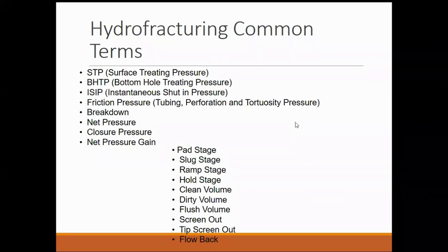Net pressure, I'll cover in the next slide, where there is a graph to show you. Closure pressure is the pressure at the time of closing of the hydraulic fracture. That is the minimum pressure required to keep the fracture open.